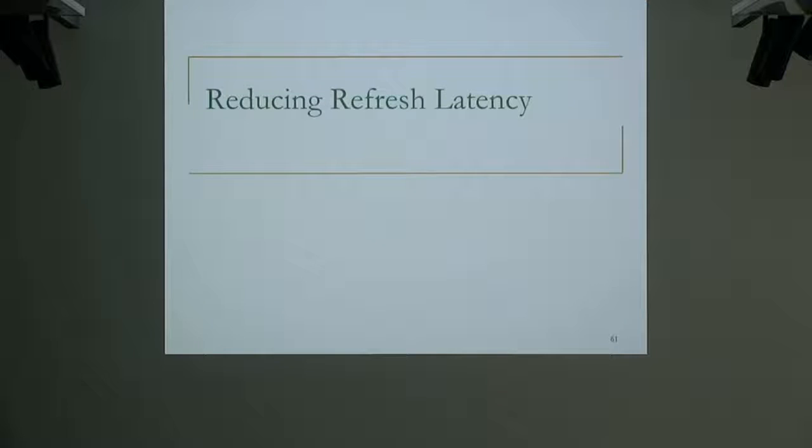Exactly. I think people have looked at that in the past, but existing DRAM doesn't do that. I agree with you. I think that's actually a very nice way, and people should look at how to reduce the area overhead of that kind of sense amplifier. Then you can actually make the interface more asynchronous, right? Right now, you're relying on a synchronous interface. Of course, this would require many more changes, but I think it's just a natural way to think about the problem.